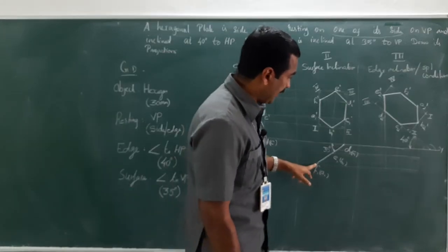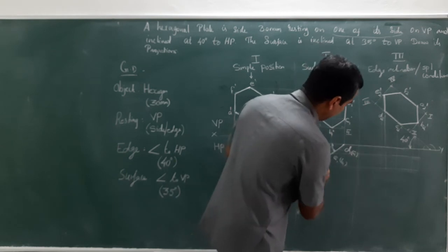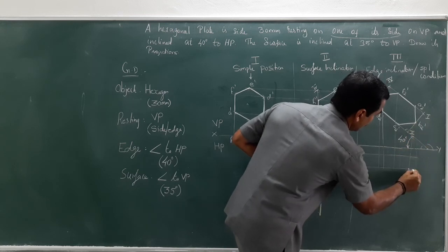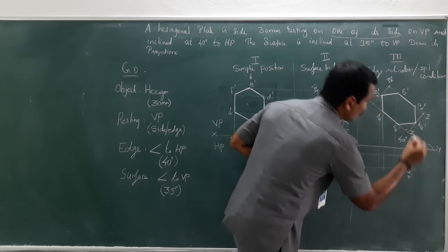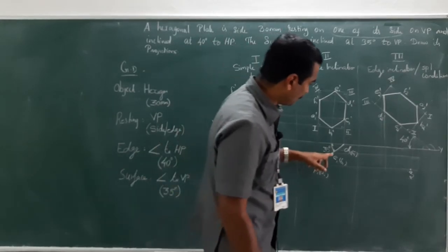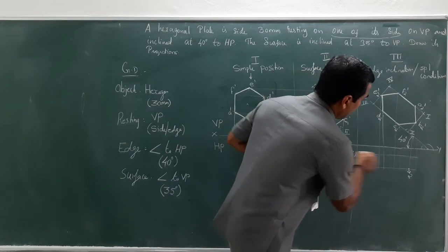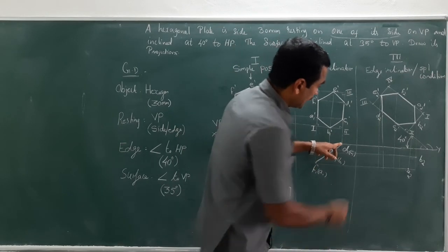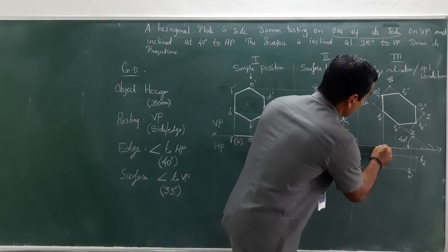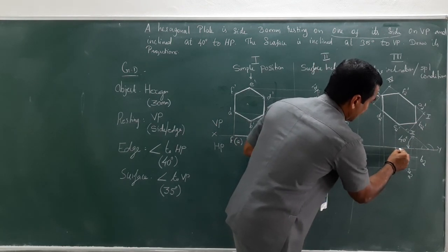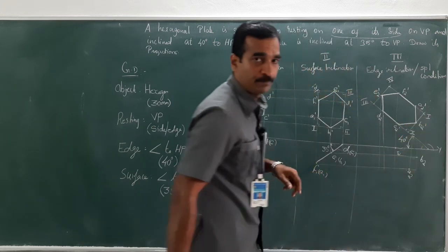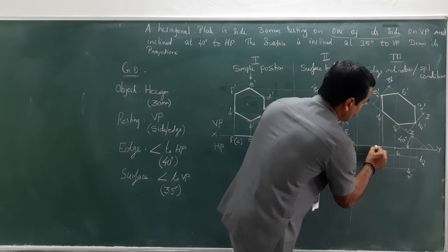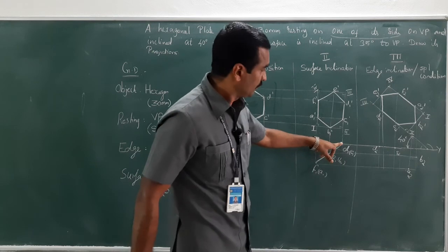Right. A is here. Where is A here? Intersection point. This is a horizontal, and vertical intersection is here. So, this is A2. Next, B. B and B are intersecting here. So, this is B2. What about C? C, horizontal projector and vertical projector are meeting here. So, this becomes C2. D, horizontal projector and vertical projector are meeting at this point. So, this is D2.